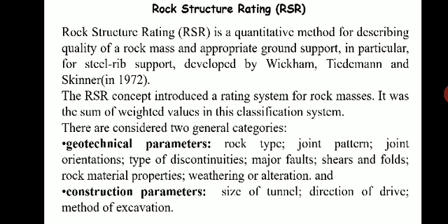Then as with any empirical approach, one should not apply the concept beyond the range of sufficient and reliable data which is used for development of the method. Because of this reason, the RSR concept is not recommended for selection of rock bolts or concrete support. So this is only supported for the construction of a tunnel with steel ribs.